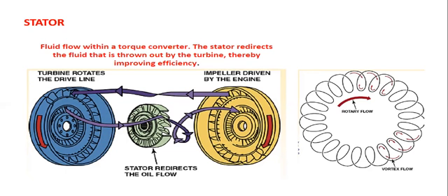So what is meant by torque multiplication? If we consider an example, suppose 1.35 newton meters of torque enters the impeller, the turbine delivers more than 2.7 newton meters of torque to the transmission input shaft. Torque multiplication occurs only when the impeller turns faster than the turbine. If you look at the figure at the right, fluid pumped into the turbine by the impeller creates not only rotary fluid flow, but also vortex flow that increases the efficiency of the torque converter.